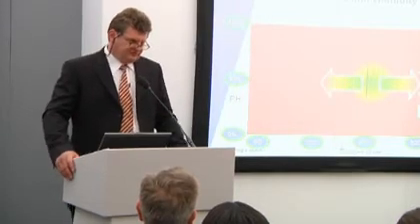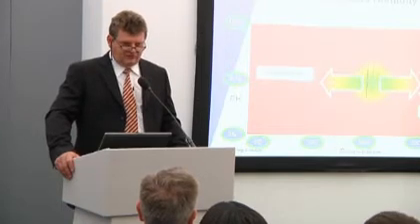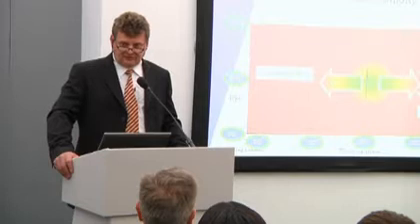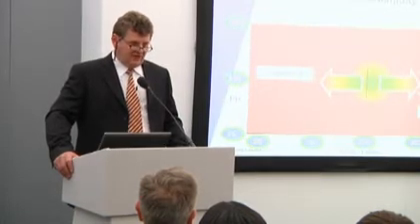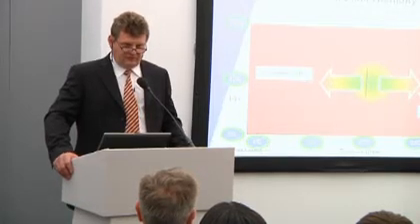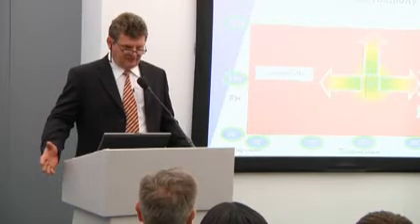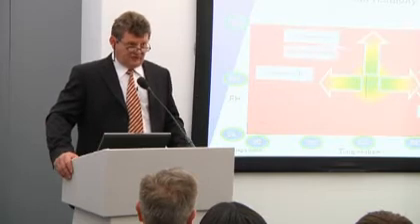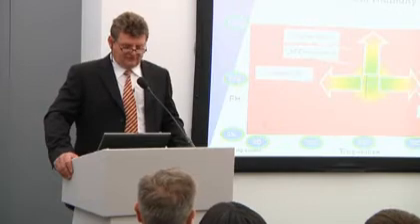Low temperatures. Now, most low temperature limits in the standards which are set are an economic, not a technical standard. These standards are set to stop people running their refrigeration equipment too cold and losing further performance. High humidities, high relative humidities. Everyone knows if we get condensation in any sort of building or any sort of equipment, that's going to lead to problems.